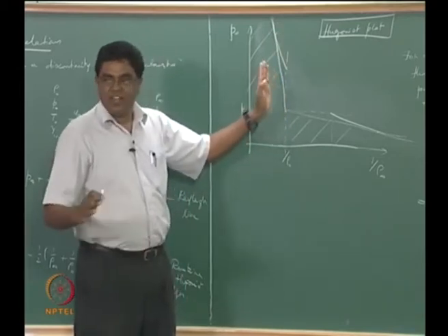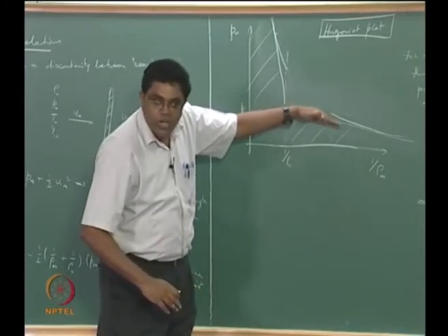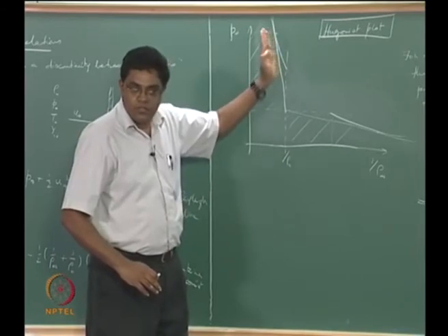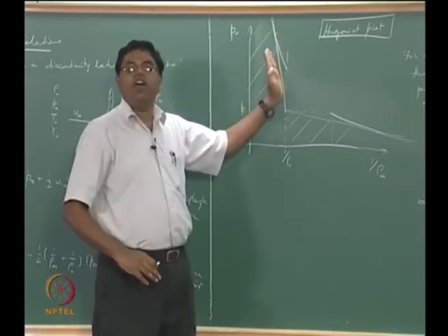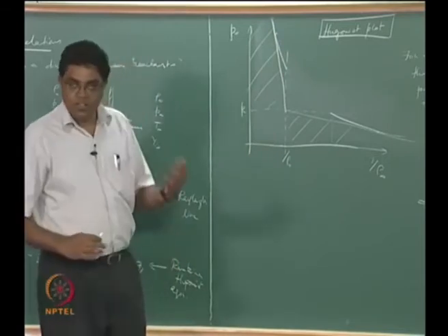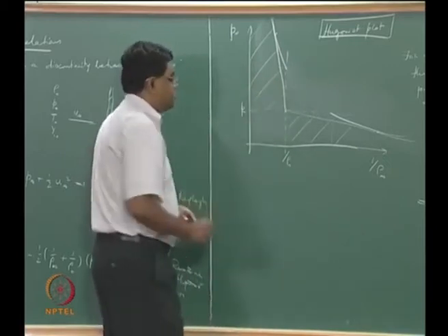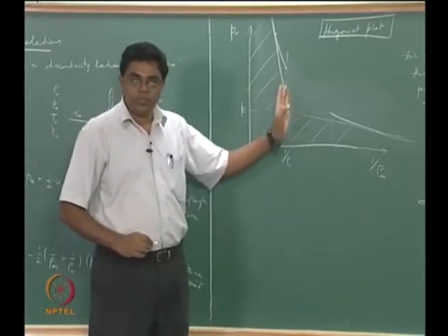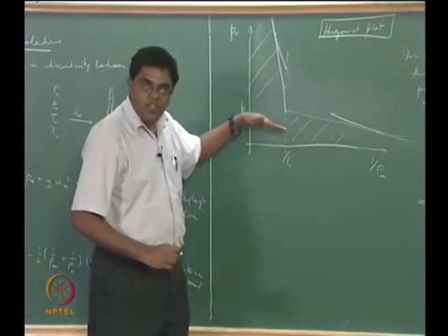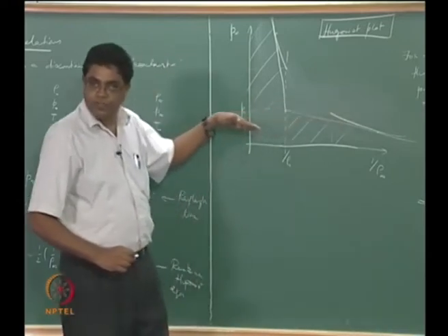It is kind of, again, just like how a zero slope is almost impossible and we are thinking about very low velocities, right. Infinite slope again is not something that we want to think about, but very high slopes mean very high velocities for which the pressure jumps but the volume didn't change a lot. So this is more like an isochoric process. That's what you started out with was an isobaric process, right.